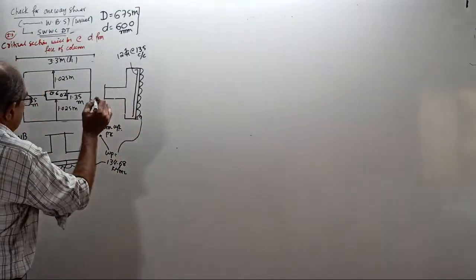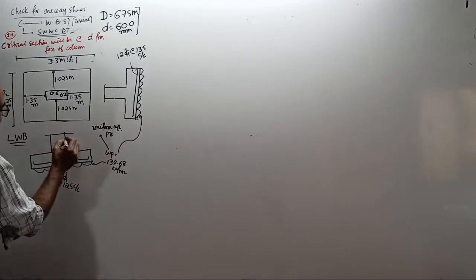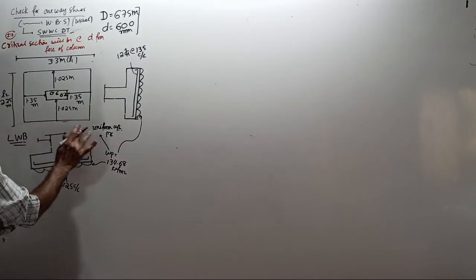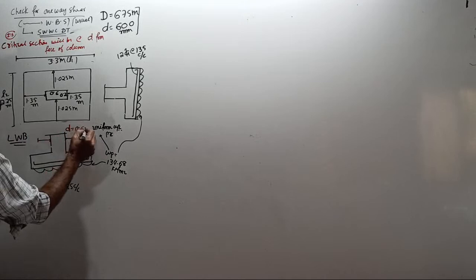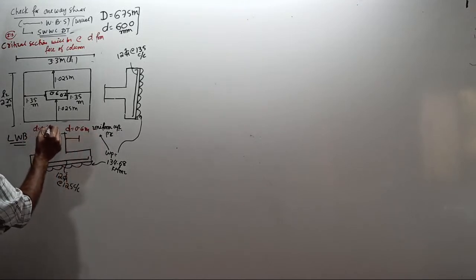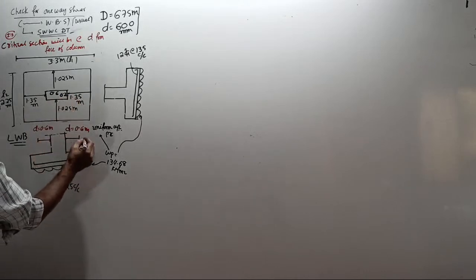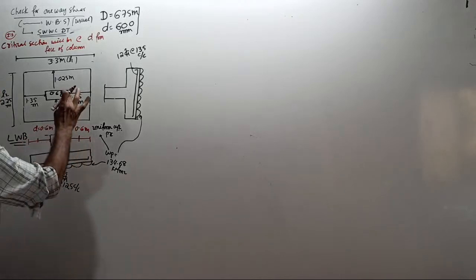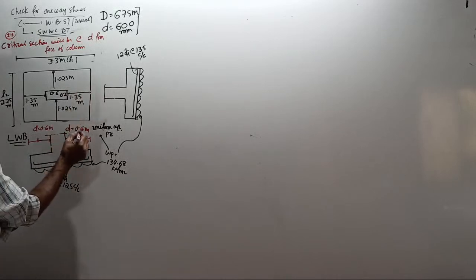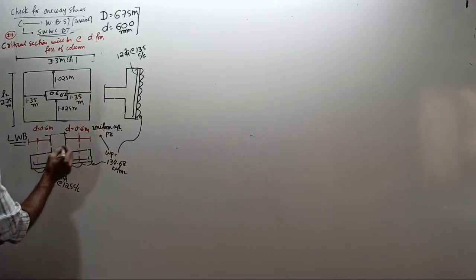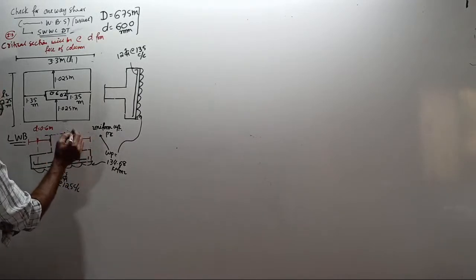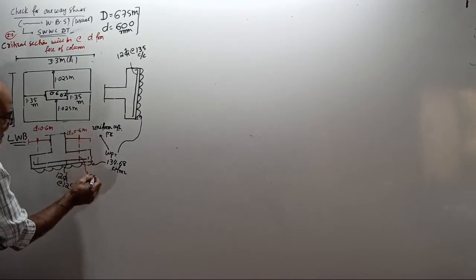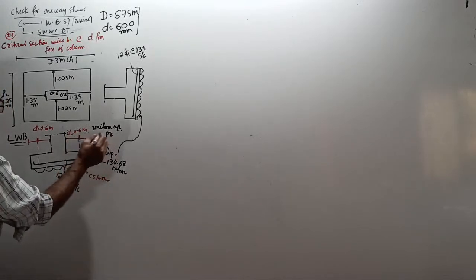Okay, now leave it. See, one critical section here. Critical section here is actually not required, I'll take the critical section here also. What distance? d equal to 0.6 meter. Why 0.6 meter? Because when you calculate, these are in meter. If it is 0.6 meter, tell me what are these two lengths first. Projection is 1.35. This is the critical section right here. Okay, everything, d equal to 0.6 meter. You write here, this is your critical section for shear. Tell the answer here. Projection.